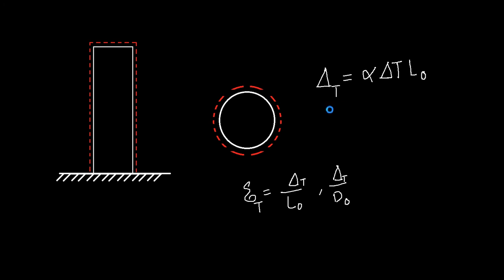for doing problems that involve both thermal effects and stresses. Wherever you have thermal stress, you need to apply different forms of this equation to find the change in dimension and the forces or supports that will be needed to prevent or contain those changes.